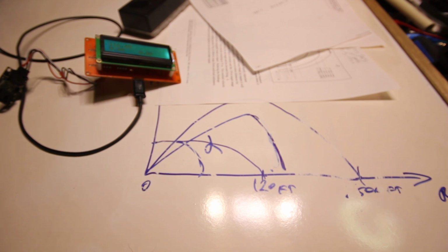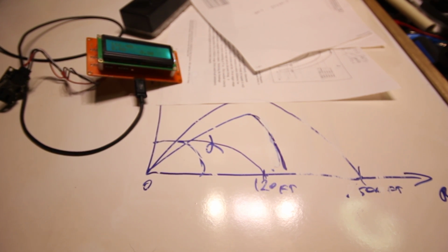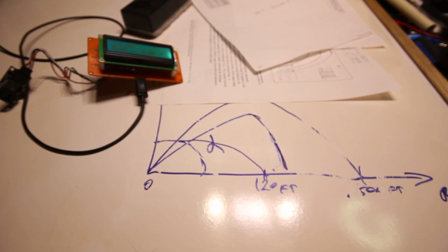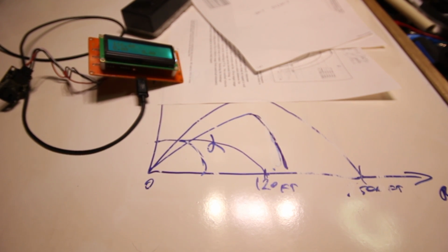I calculated the terminal velocity of a typical paintball, and it turns out to be about 19.5 meters per second, or 60 feet per second. And it also happens to be, I'm talking about regular field mid-grade quality paintballs, a 50-50 breaking velocity. Meaning that half the paintballs will break at 60 feet per second, striking a soft target such as your chest plate or maybe your arm.